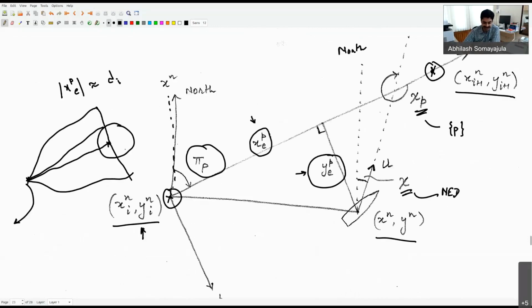This is more robust than the circle of acceptance method, but nevertheless, it still fails if my ship is headed in the opposite direction, like I see here. In which case, you'll never be assigned the next waypoint. So there is a pinch of salt to take it with. Sometimes you may have to program some other logic in order to make sure that this guidance methodology works seamlessly on your applications.